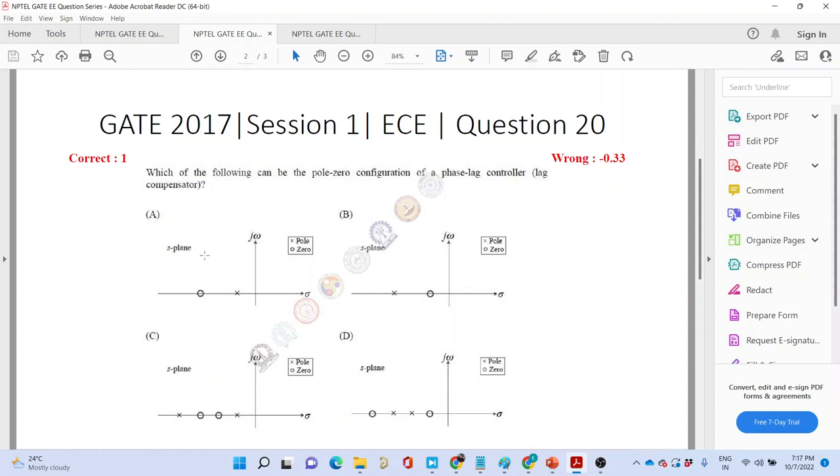So these two poles are in the complex plane, not on the real axis. Say one is closer to the j omega axis, and the other pole is far away from the j omega axis. The one which is far away, the decaying factor, the e to the power minus zeta omega n that you see, would be much faster as compared to the oscillations caused by the pole closer to the j omega axis. Are you getting my point? Yes. Okay.